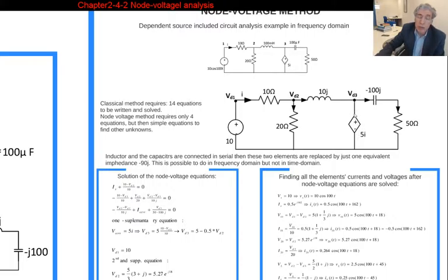This element current is an unknown, and we've got to write it here. The third element, as we already said, is the equivalent impedance, and VD2 over this impedance gives the current of this impedance. This is what we have written here. So we've got three equations now.